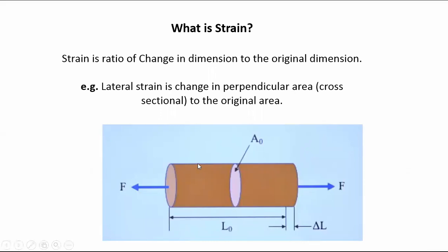The engineering stress strain diagram tells that we assume the cross-sectional area is constant even after applying force, and there is an elongation. This is for our ease of calculation, because we engineers like things easy, and it has practical application and significance. Even though you can draw a true stress strain curve, for simplicity of calculation we use the engineering stress strain curve, and in that we consider the diameter constant over the whole experiment.